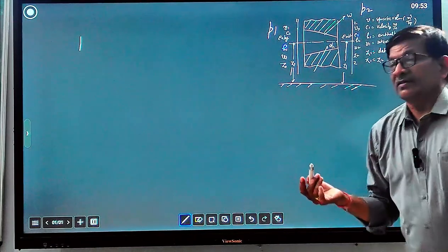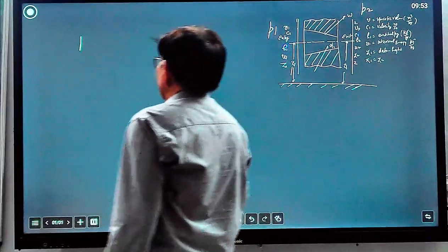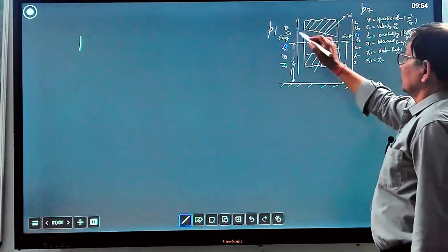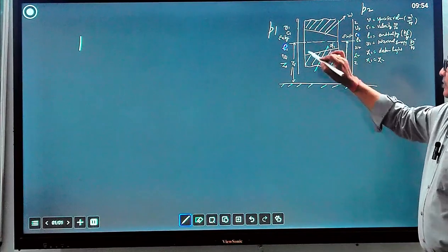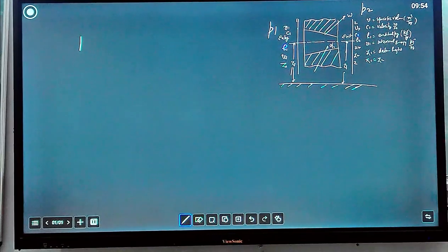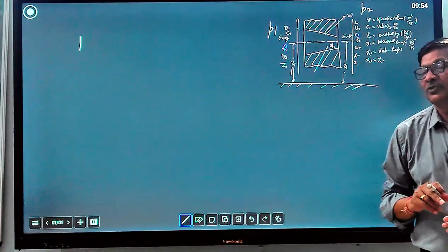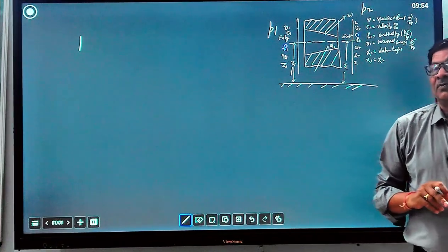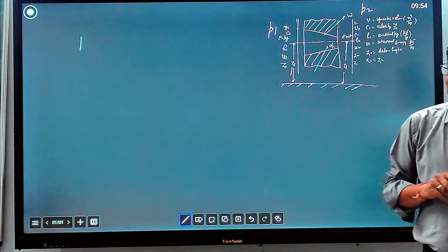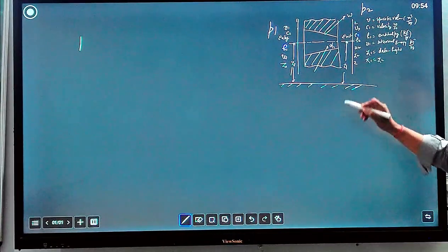Pressure at inlet in kilopascal, pressure at outlet in kilopascal, or pascal, you can define. So writing the energy balance equation at entry and inlet, because there is a steady flow energy equation, no accumulation inside the nozzle. Generally we take the nozzle body surrounding surface as insulated, so there is no heat dissipation from the nozzle to outside or from outside to inside. And the nozzle is not a device which performs any work. So these terms will become zero later.